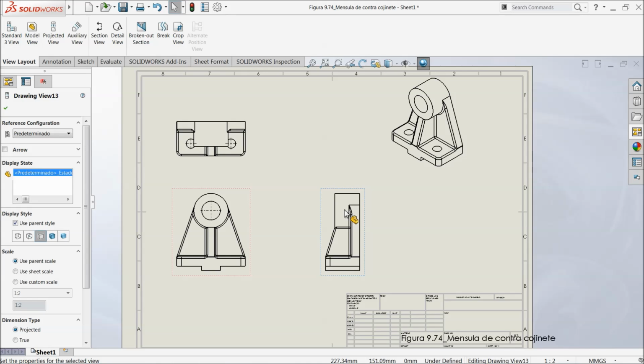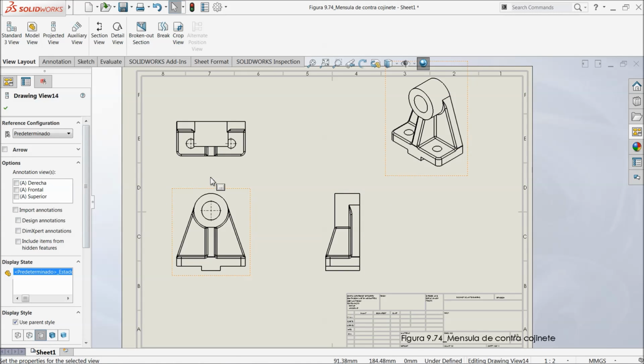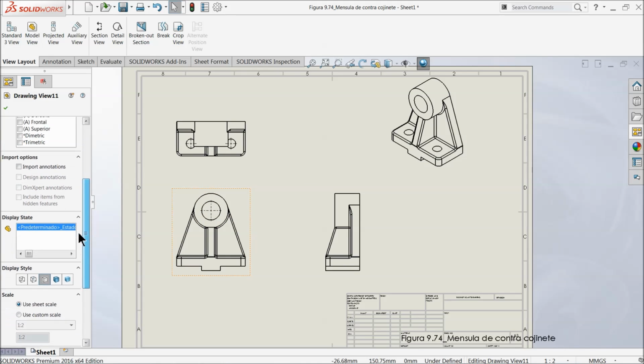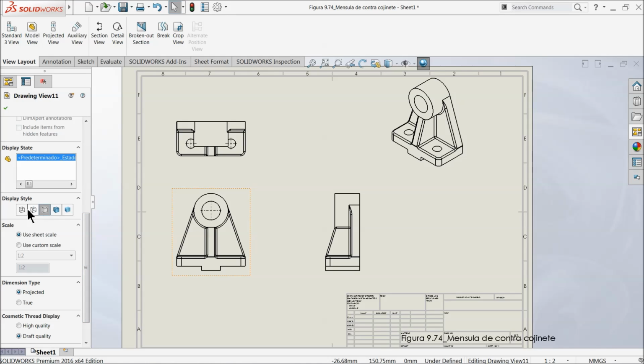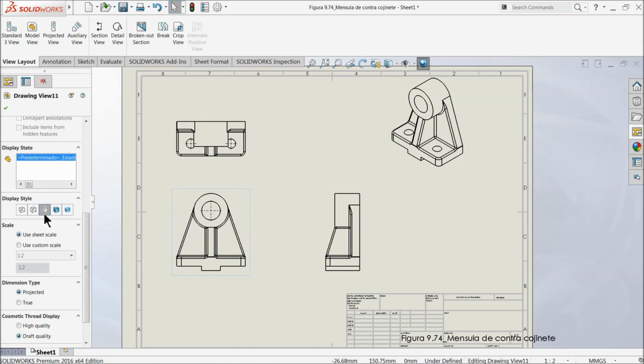Now we will see, if you select each and every drawing, a window will pop up here. Let's say this one. Now here you can define the display style. See, shaded, then shaded with edges, 2D with hidden line, frame, wireframe. Almost everybody prefers 2D with hidden line.